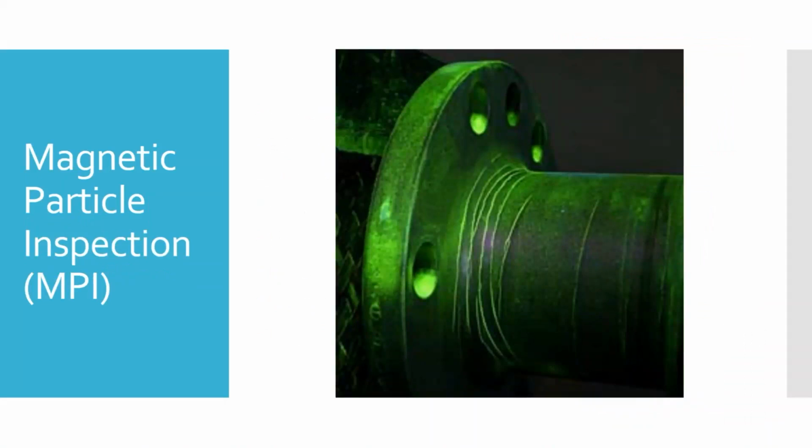So, mag particle inspection. Here is a picture of a part that's undergoing magnetic particle inspection. What do you think we're seeing here? Let's go indications. What do you see indication-wise? What's that? Think those are scratches? Think those are shear stress? Shear stress creating what? Those are cracks, okay? Those are cracks. Any other indications you see? So what kind of an indication are those cracks?